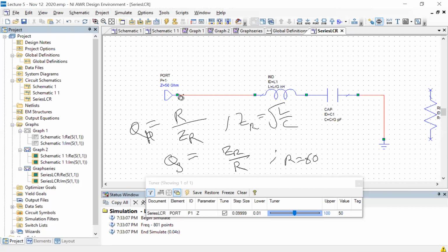However, at very low frequencies, these constraints don't matter. You don't have 50 ohm sources. You can have a source with a very, very low source resistance, because an ideal voltage source has zero source resistance, and such sources do exist at low frequencies of kilohertz. And these are the kind of things you use in your lab experiments. And then you can make largish inductances as well at low frequencies without any problem. Just have to keep winding more and more wire.